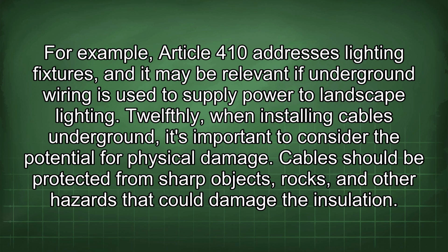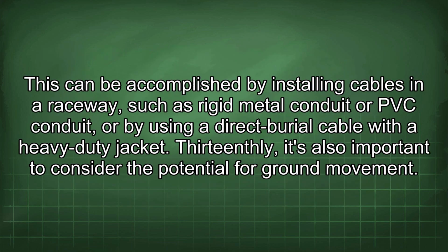Cables should be protected from sharp objects, rocks, and other hazards that could damage the insulation. This can be accomplished by installing cables in a raceway, such as rigid metal conduit or PVC conduit, or by using a direct burial cable with a heavy-duty jacket.